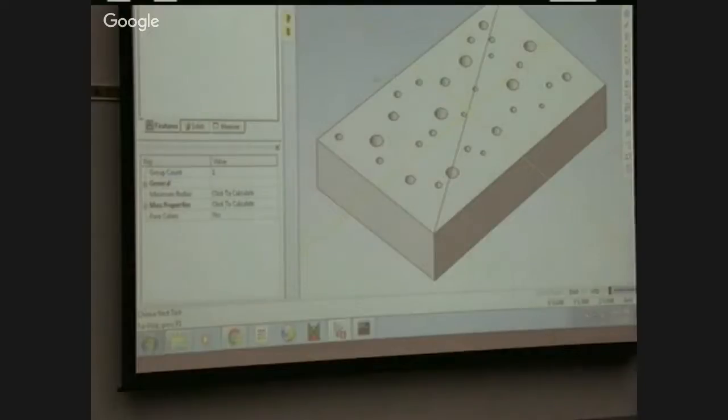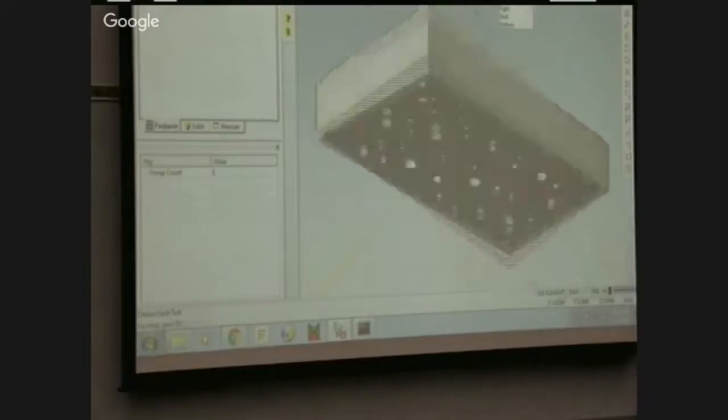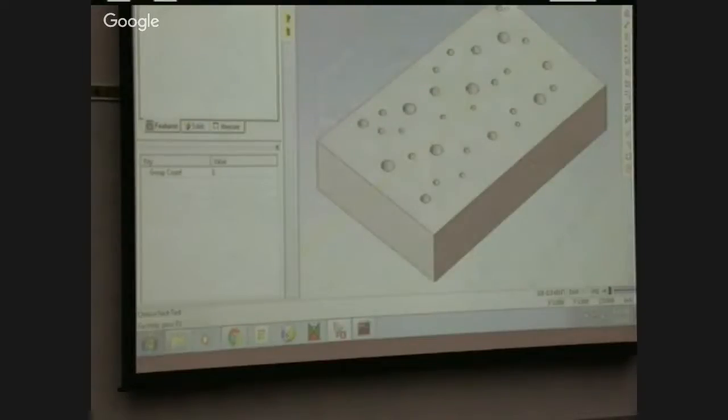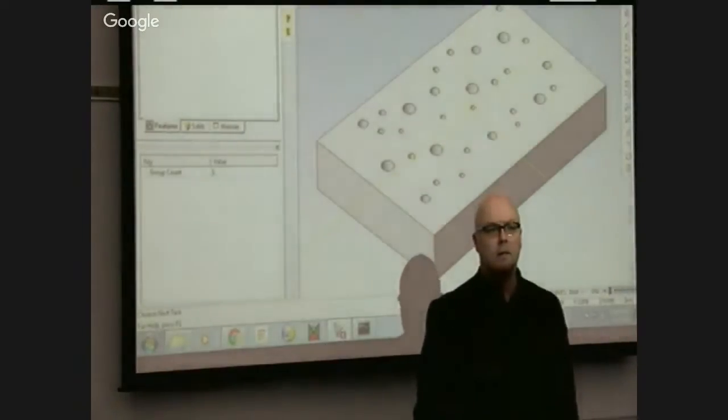Right? So if I say I want the origin to be on the bottom, I can say edit, orient part, align Z. I'm going to select the face first. Sub elements on, highlight on, select the face, and edit, orient part, align Z. And apparently I selected the wrong face, but that'll also put it in the center of that face. All right, so there's 3 ways that we noted that we could adjust the origin of the workpiece.